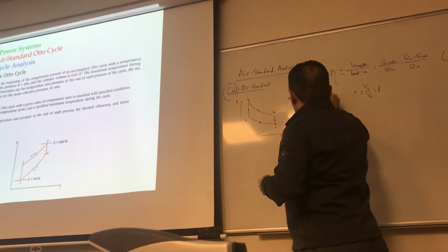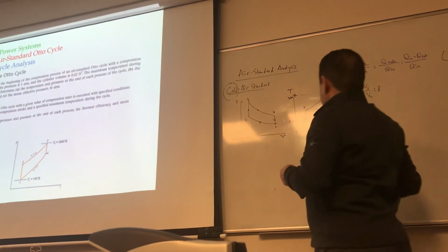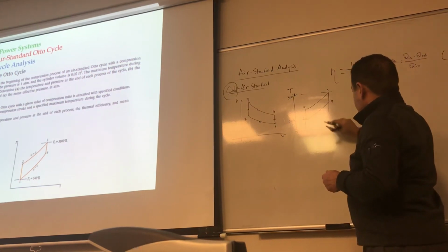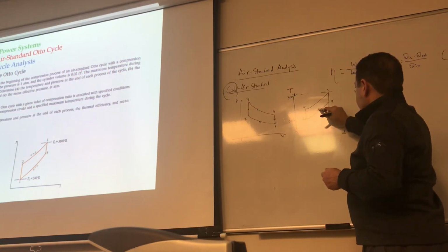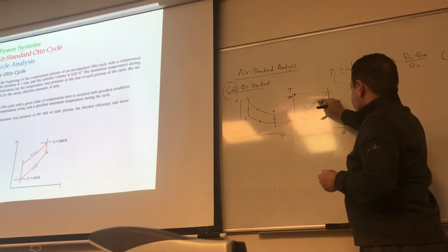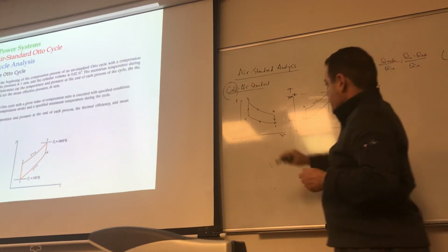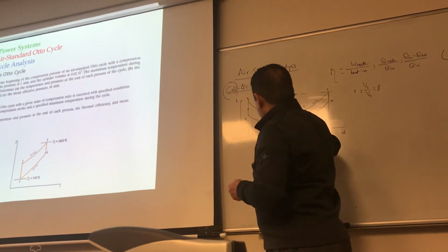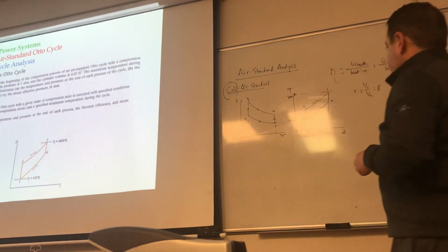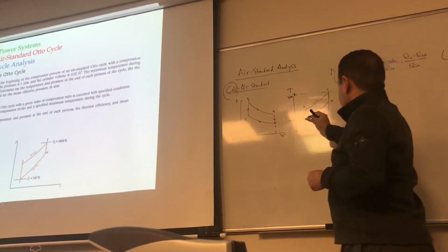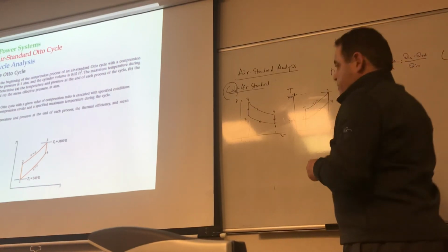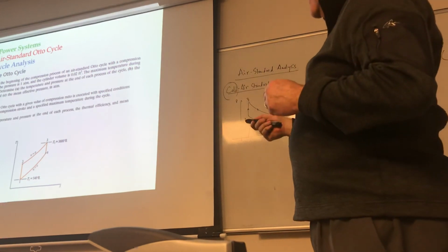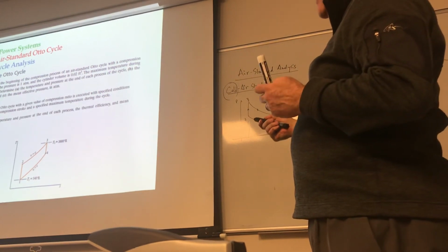The 2 isentropic processes, and the 2 where V is constant. So if this temperature is 540, this obviously has to be 3600. The maximum temperature during this is 3600, and then you're asked to determine all 3 questions.